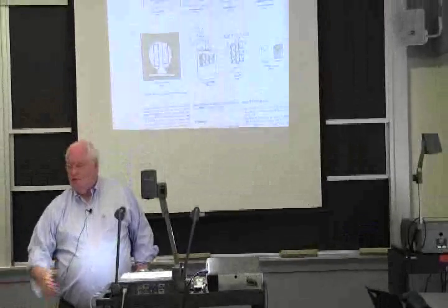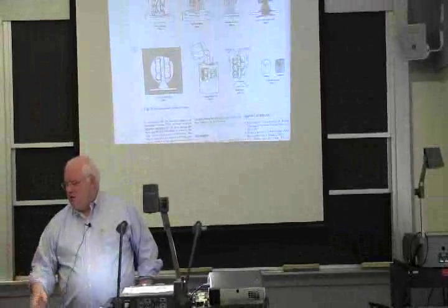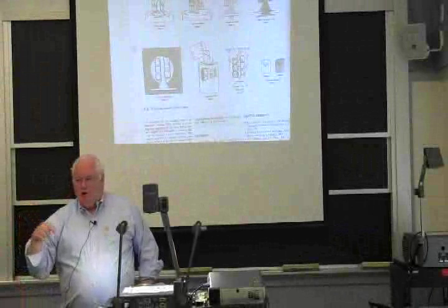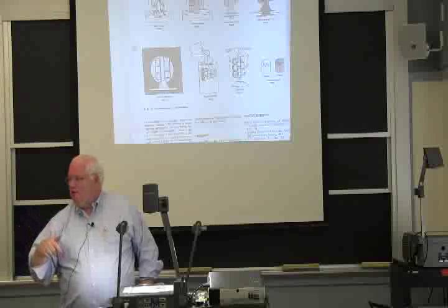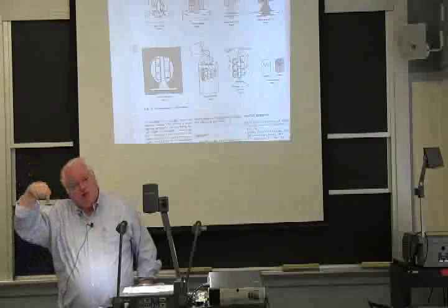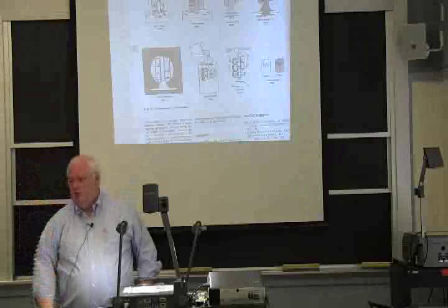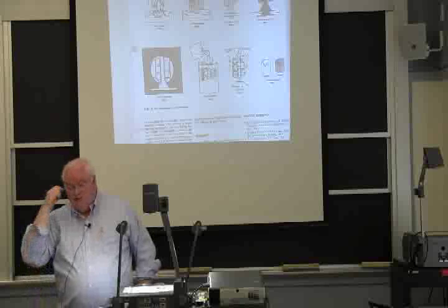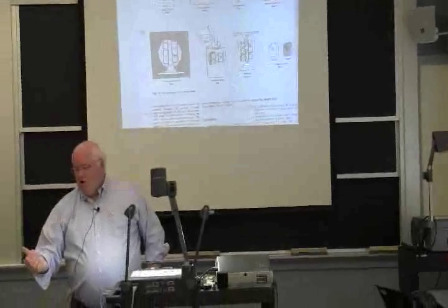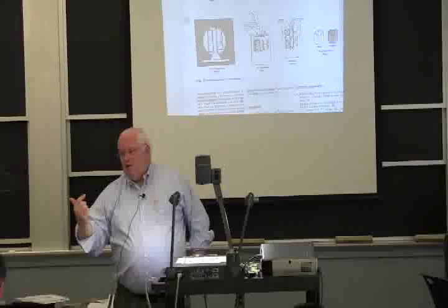And you end up with a single crystal turbine blade, which costs $6,000 a piece, after you've done all the metal finishing and everything else. The holes in there are either laser or electron beam drilled under high intensity, or you can take a plunge EDM machine and plunge the holes in there, because eventually, in order to get high efficiency in the engine, you want to put cooling air through there.